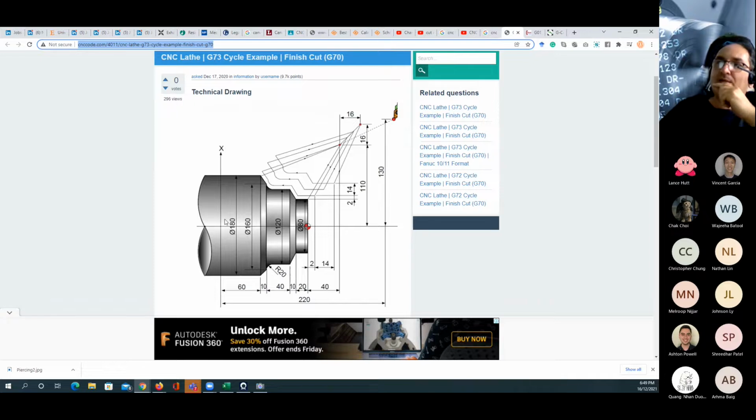of using the G02. Now you can see that this part can be a good exercise for you. You can see the number of the codes we have in here, but these codes actually are not going to generate the primary shape before we have the finishing operation. I mean, you cannot start cutting like that. What you need to do is first shave and peel off the part and make it as a stepped shape before you do this operation or this movement to generate the final shape.